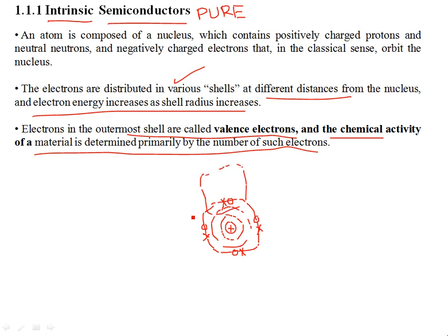So there will be another, for example, let's say a silicon atom, then there is a second silicon atom. So you will have these 4 silicon atoms to complete an octet structure, and this octet structure, you see, continues. There will be again some valence electrons left over, which are going to bond with the next neighboring silicon atoms. So this picture might not look very great, but you can understand what's going on. You need to have the sharing of electrons with the other interacting silicon atoms.